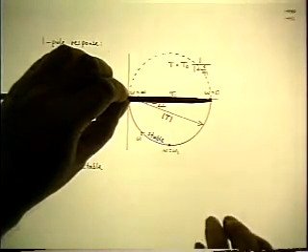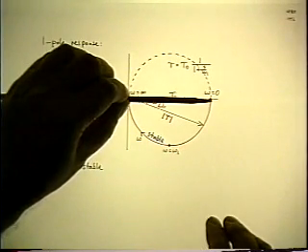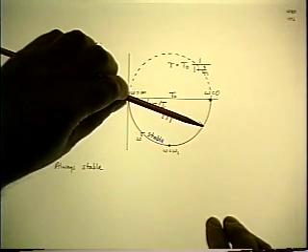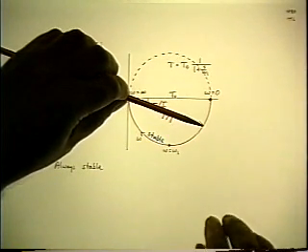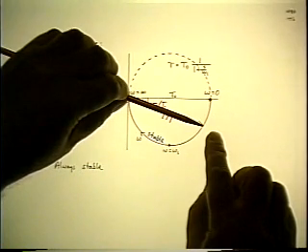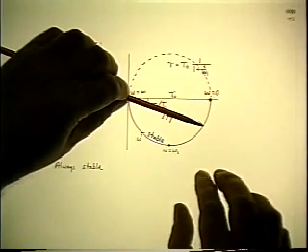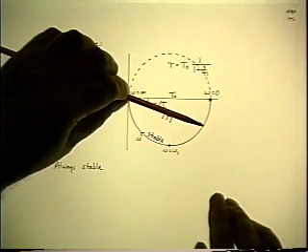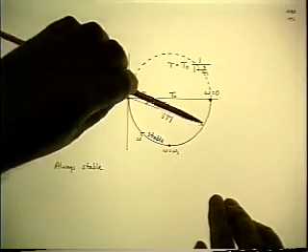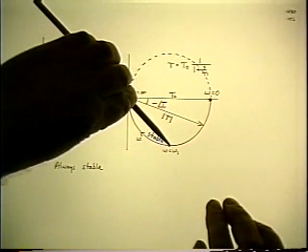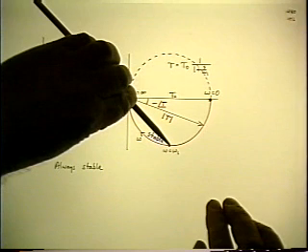Then you take a higher frequency and find the magnitude of t, which is now a little less than t0, and it starts to build up a lagging phase angle. So you mark the end of that one with some arbitrary value of frequency. The first one of any particular interest is the corner frequency itself. If you put s equals j omega 1, the magnitude is down to 1 over root 2 t0, and the angle is now 45 degrees.